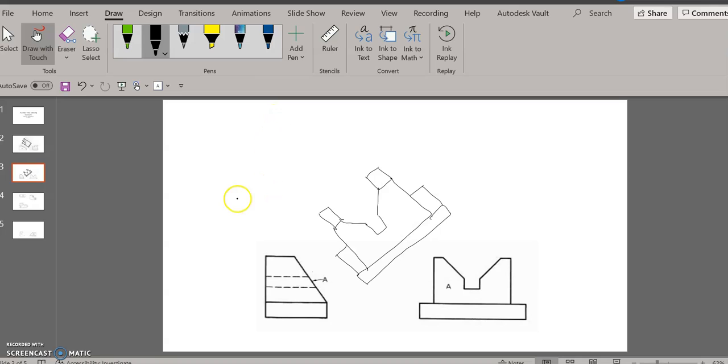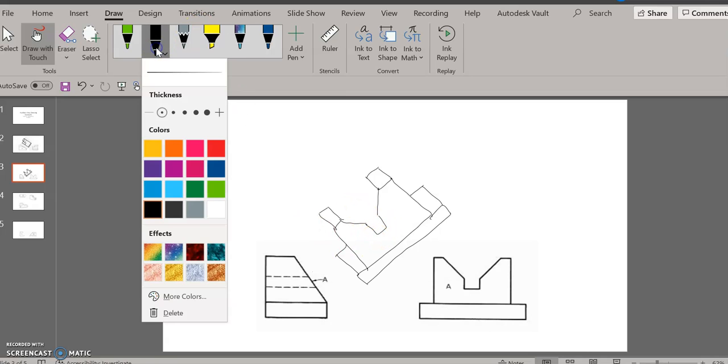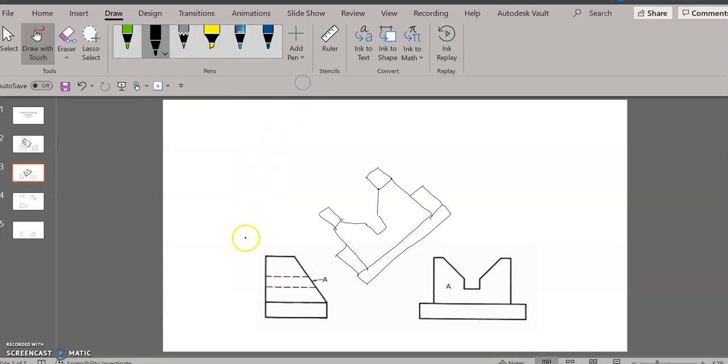Okay. What I'm also going to have to do is draw this angled surface as well, but I need to know where they begin and where they end. And there's also a projection, the slot I'm going to see from the top. So I need to go ahead and draw those angled surfaces. I need to project them up from this back edge. Okay, so I'm going to use those lines to help me draw the angles.